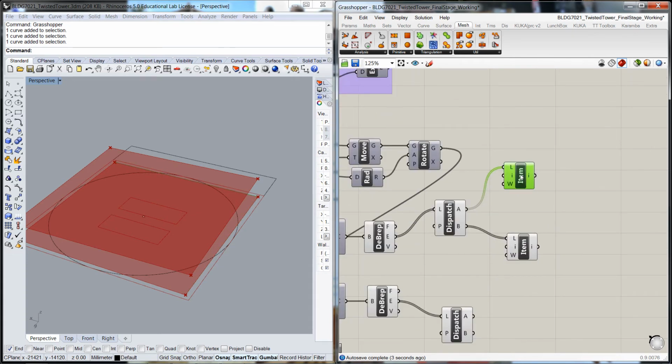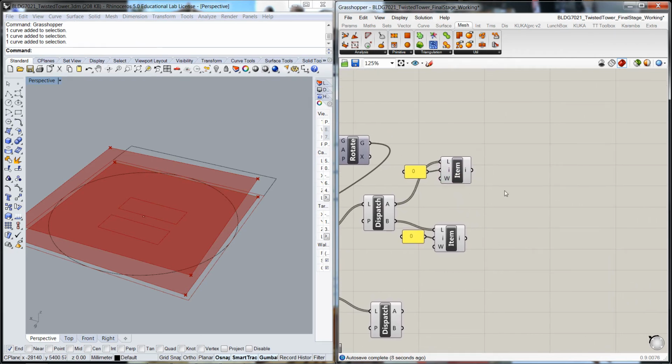So now what I've got is one half of these two lines on here and the other half on these two lines through there. So the list item that I want to pull out is the first one, so I'll do a panel. So that will be the 0 item, remembering that the list's numbered off at 0. I'm going to copy that and I'll plug that into the item number through there. Okay, so what it's going to do is it's going to interrogate the first item in my list.